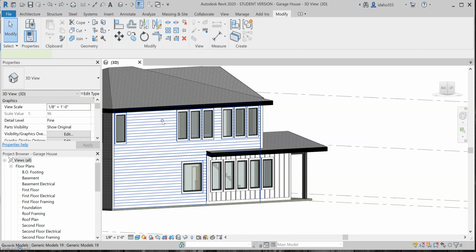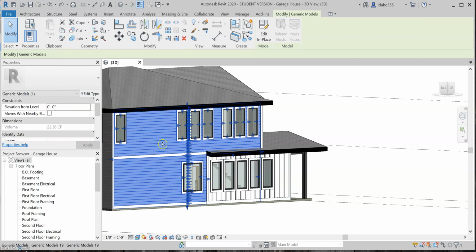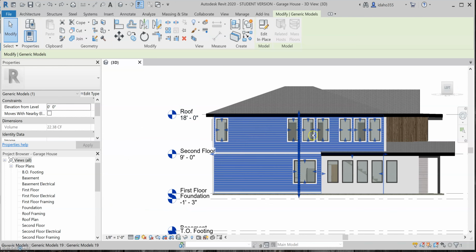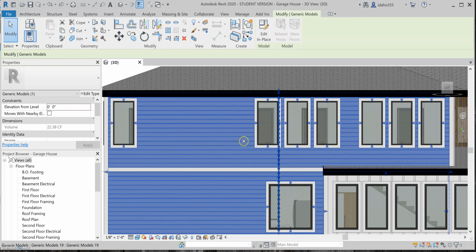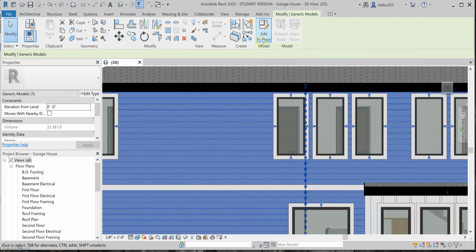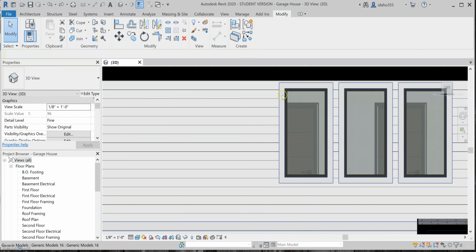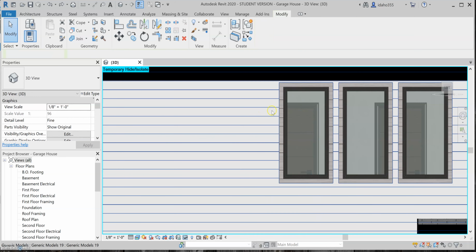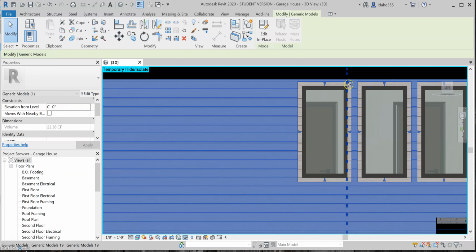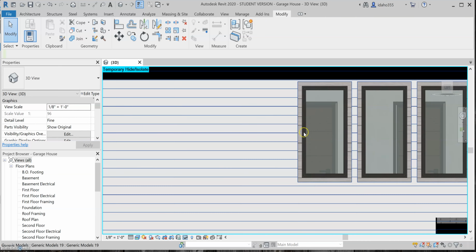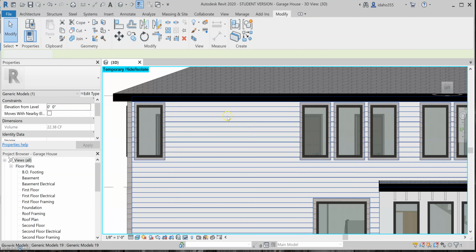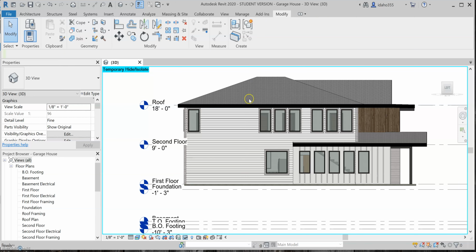So the hard part about this was I obviously have this extrusion, but I've also got these windows in here. So you got to figure out, okay, if I just ran this wild, none of these windows would be cut out and it would just show clapboard the whole way along. So what I did was I clicked on this, and what I've actually done is I've created void extrusions around all of the windows in the actual clapboard siding. So that's kind of what I've done thus far.